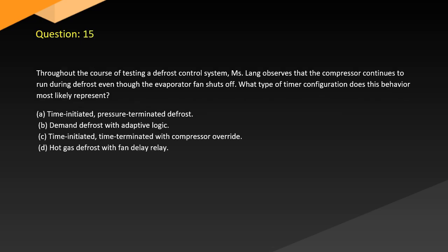Question 15. Throughout the course of testing a defrost control system, Mr. Lang observes that the compressor continues to run during defrost even though the evaporator fan shuts off. What type of timer configuration does this behavior most likely represent? A. Time-initiated, pressure-terminated defrost. B. Demand defrost with adaptive logic. C. Time-initiated, time-terminated with compressor override. D. Hot gas defrost with fan delay relay.